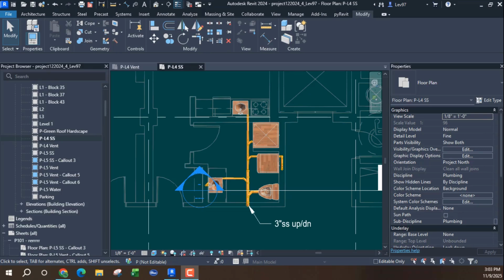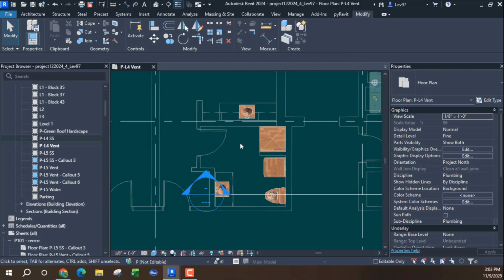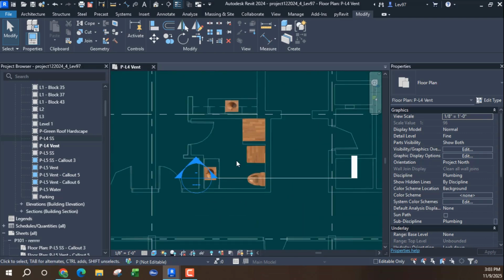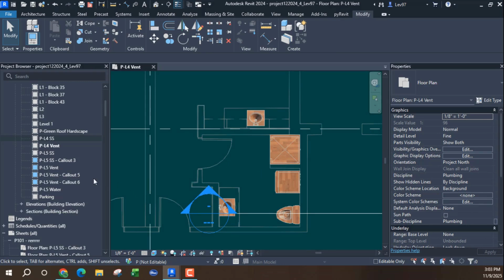Okay, let's continue with this plumbing drawing. So I just finished the sanitary, so let's go to the vent system on the 4th level for this particular bathroom. Okay, so just the opposite of the sanitary. To get the waste out, you use your vent system to bring air into the building. And the best way to do that is to look above your plan to see what walls are available.